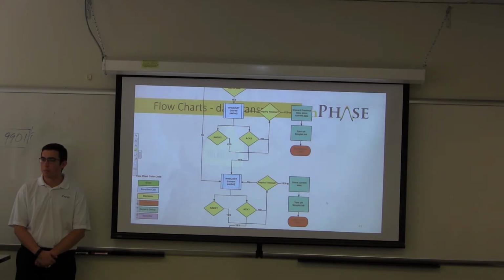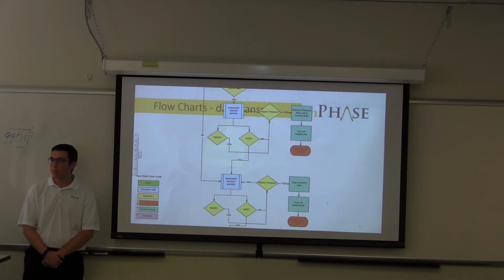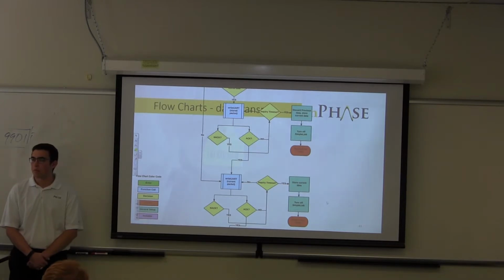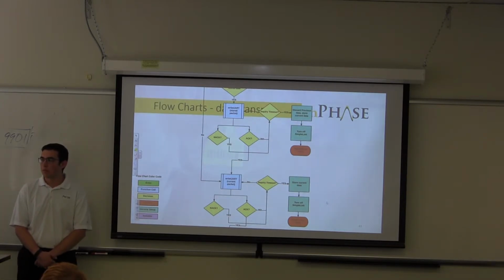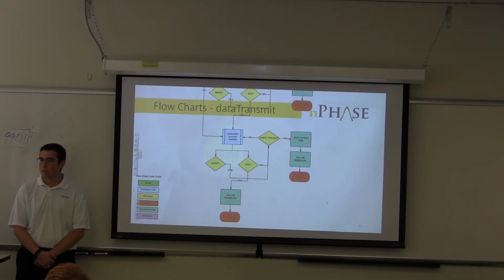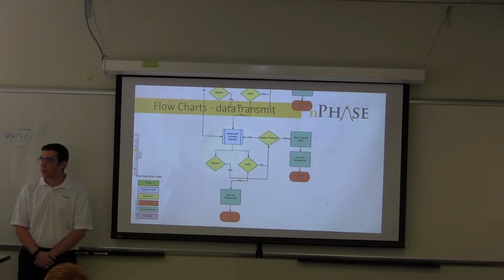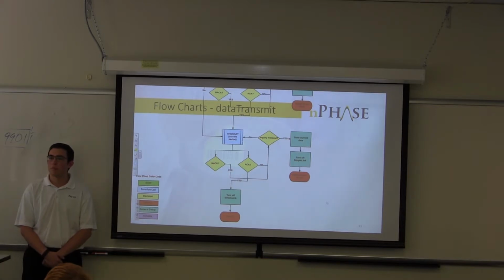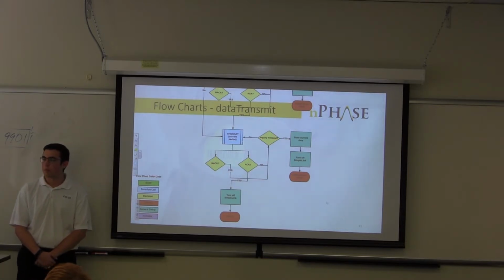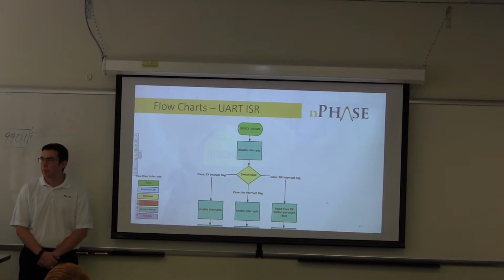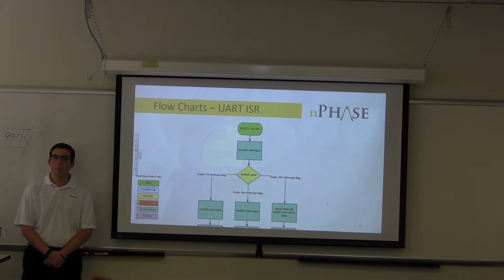It's going to check 3 times to see if we're going to get an acknowledgement or not. And if we do, then we move on to write the next packet. If we don't, it's going to discard that data and store current data in, and then turn off the SimpleLink and return an error code. So we're going to send that current packet and do the same sort of error checking. And then if we can successfully send that packet, we're going to turn off the SimpleLink and return from that function.